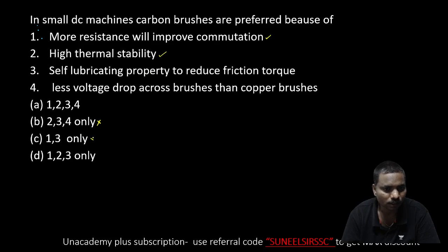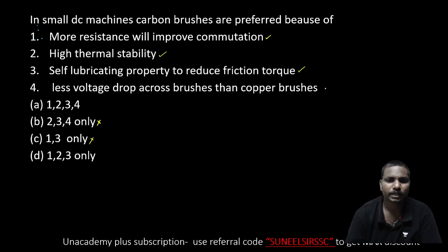So it is 1 and 2 is not there, so we can eliminate this one. Okay, and self lubricating property, yes, because it is a non-metal and it is soft in nature, self lubricating. And less voltage drop across the brushes than copper brushes. No, it is not correct.